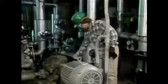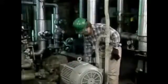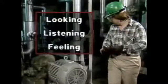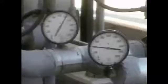Pumps can experience a variety of problems, and each problem can have a variety of symptoms. In spite of that, there are some general types of operating checks that can be made on all pumps. These basic operating checks relate to 3 of your senses. The checks involve looking, listening, and feeling for symptoms of pump problems. Looking for symptoms of problems often starts with instrumentation for the pump.